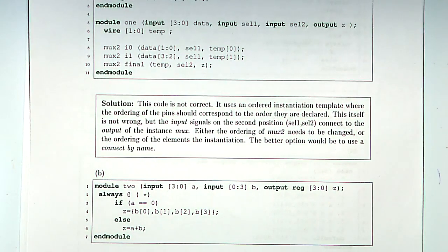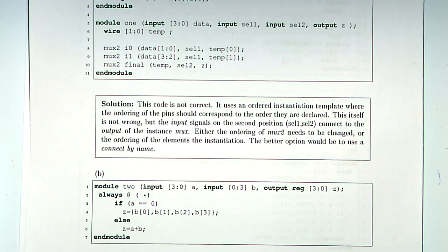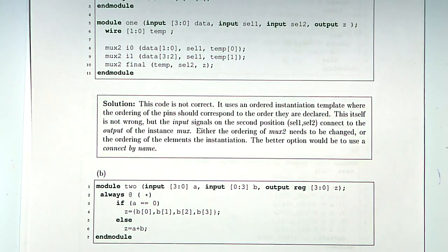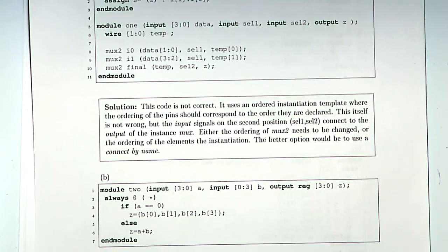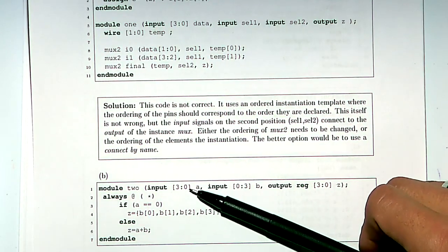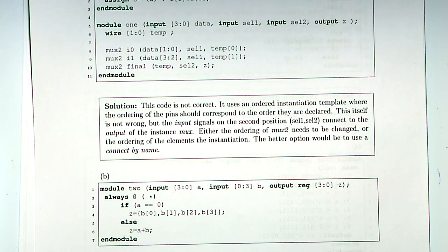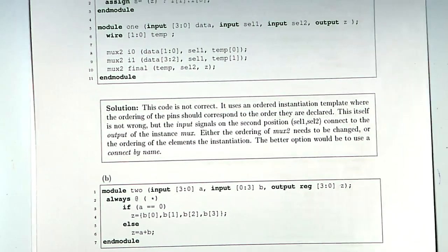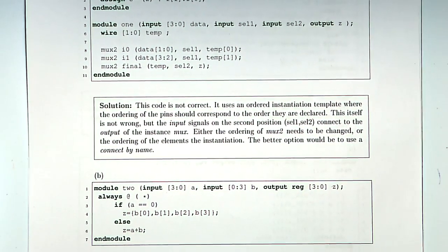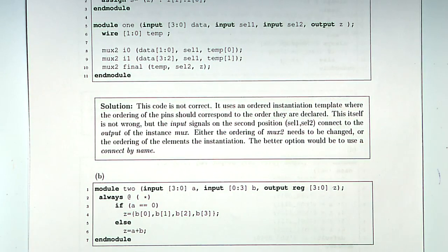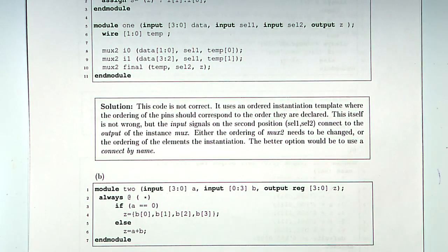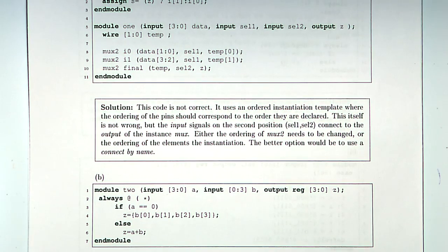Oh yeah, so that's fine because Verilog supports either type of ordering anyway. So the question was whether or not the issue matters here with this 3 to 0 and 0 to 3. These are just different customs. You can actually code it either way. So you can code it as a decreasing order for any typical binary number, or you can encode it like an array of bits. Yeah, it will change representation. In this case, the 0th bit would be the most significant bit, which is actually not that intuitive, but it's still allowed.